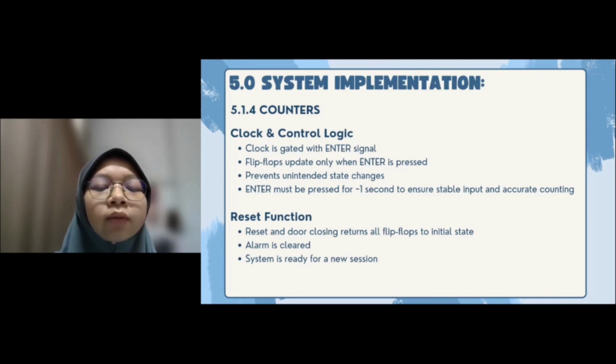In counters, we have clock and control logic. The clock is gated with the enter signal. Flip-flops update only when enter is pressed. This is to prevent unintended state changes. Enter must be pressed for 1 second to ensure stable input and accurate counting.